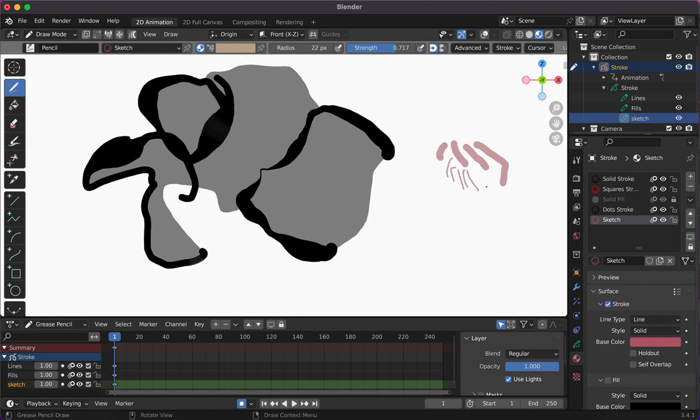Now, on a Macintosh, it's difficult to see the strokes as we're making the strokes. So that's just a sort of a problem with Blender. One way to do it is to put a fill on there. So as I'm sketching with the fill, I can see the line, and then later I can just drop the fill off if I need to. So that way I can see as I'm drawing with the draw mode where the cursor's going, and I can be doing my sketching, and then I can just turn off that fill layer.